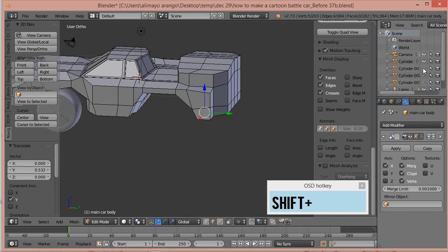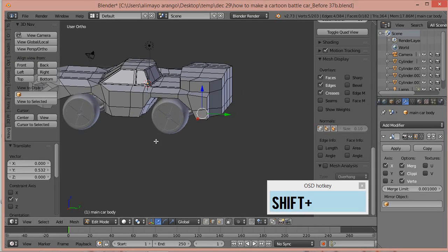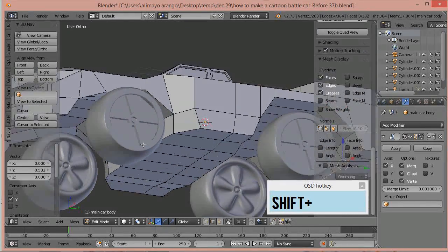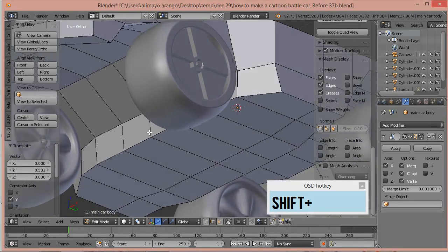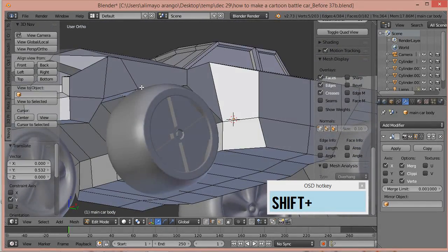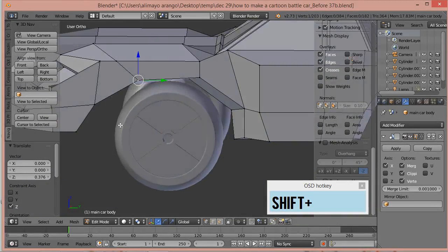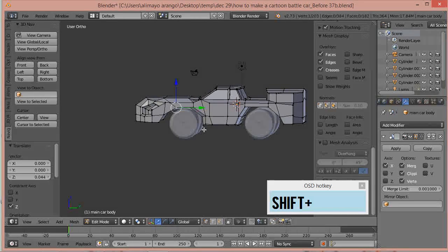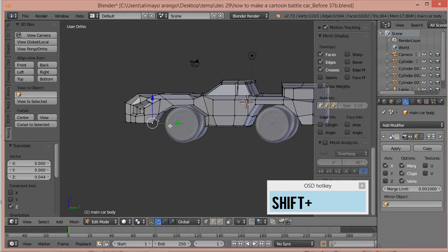Now let's bring the tires back by selecting these eyes again. Still have an issue here. Holding shift and middle mouse button to pan, rolling the middle mouse button. I'm going to go to vertices select here. Just pull that up some like that. Select this vertice, pull this back some. I'm selecting this vertice just to move this manipulator temporarily out of the way. I'm going to pull this in some here.